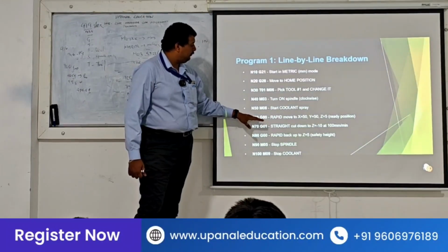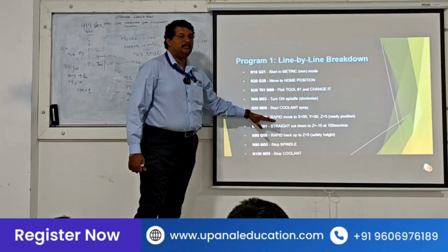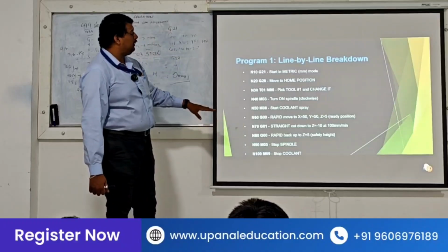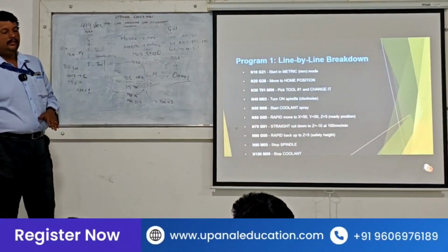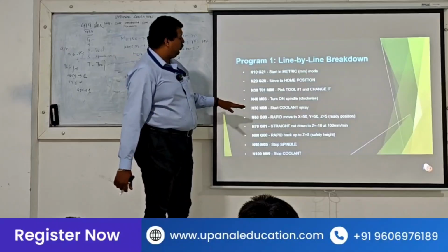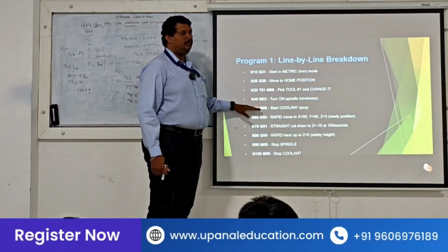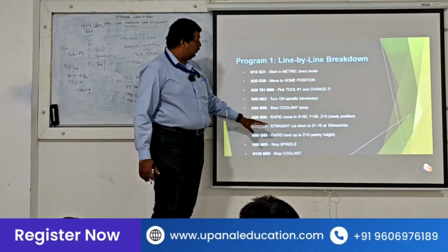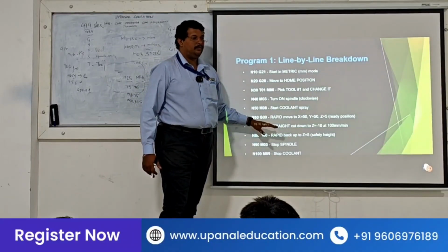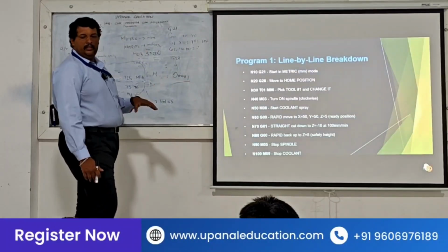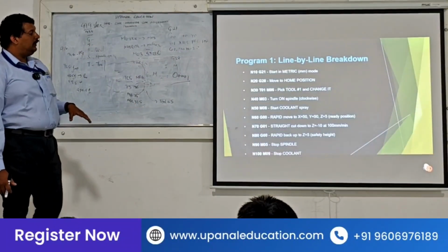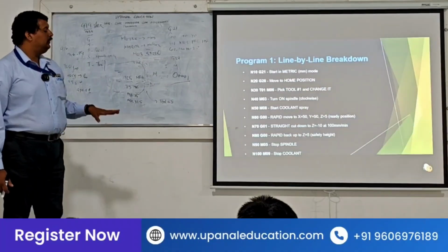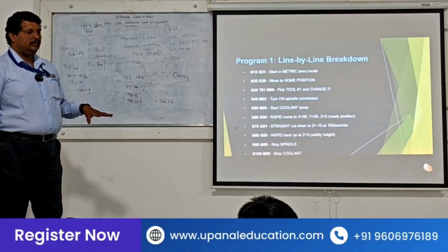Then next M08. I am telling it to start the coolant. Once the coolant is started, those are all settings. We are setting the machine. Then we start the program. So first G00. We will tell G00 XY value, go to that position. Then after that, we will tell G01, G02, G03, whatever it is.